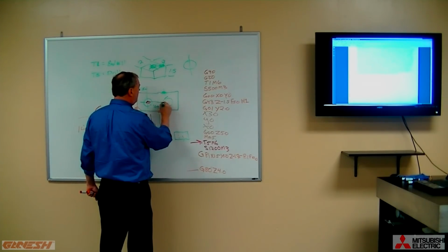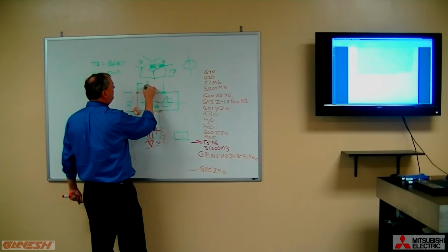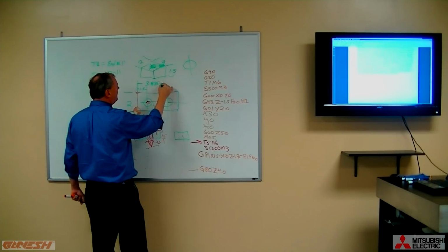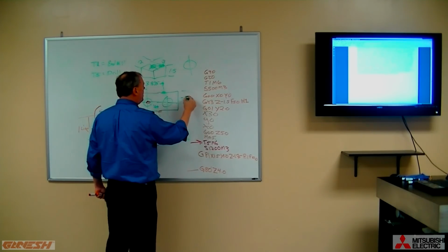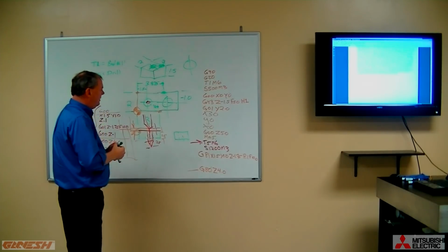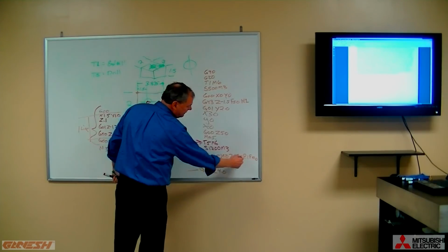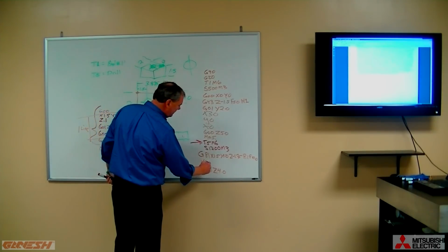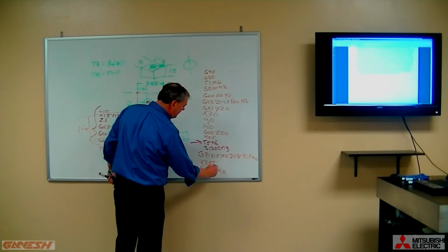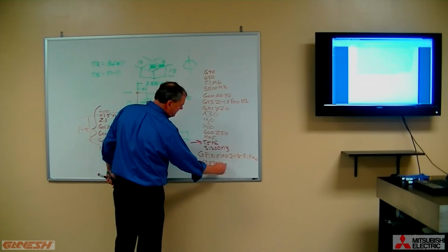And the second hole is sitting at 3.875 over in X, same distance in Y, so it's minus 1.0 in Y. Once I set up my drill cycle like I did here with all the Z and the R, I don't have to do anything but say X and now provide the new coordinate. 3.875, Y1.0.